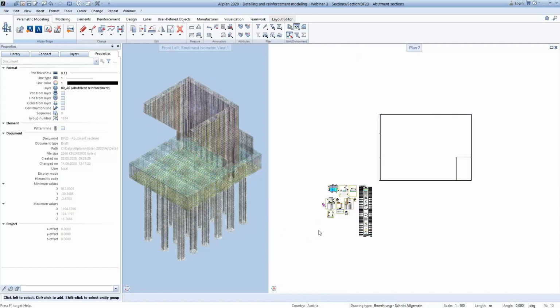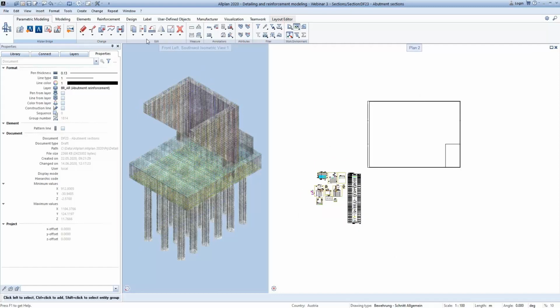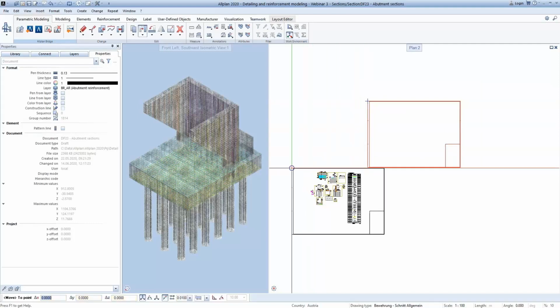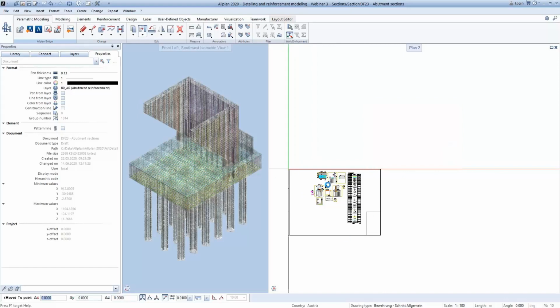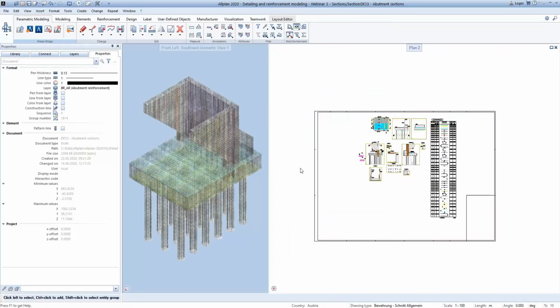After the layout border has the correct size, we can start to arrange the components into this border, and we can also use the properties window on the left side and set the format of construction line for the border, and in that way the border will not be visible while printing.